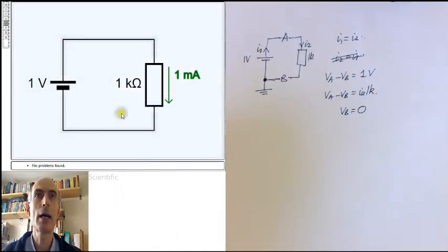If you're interested in how this simulator did get an answer, it's because this simulator makes that arbitrary choice for you. If no node in a circuit is defined as being the 0 volts point, this simulator will just pick one. Most simulators don't do that.